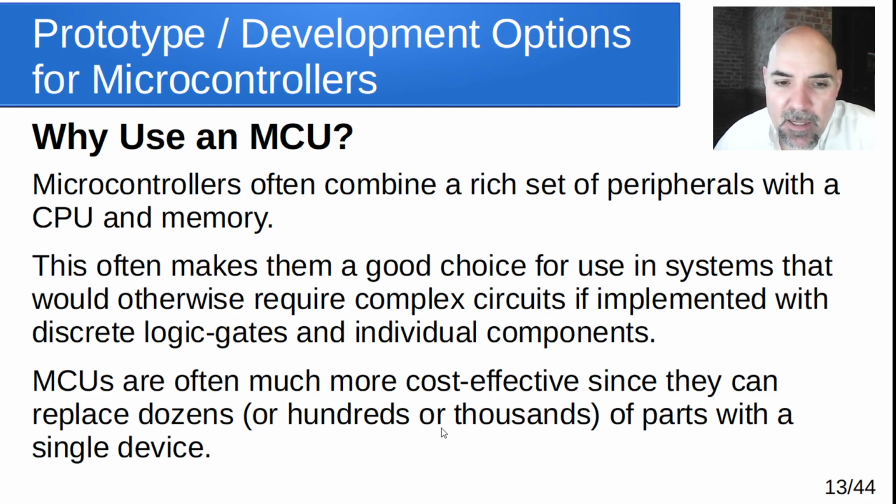And they're also very cost effective for two reasons. One is they replace a whole bunch of chips with one chip. The other one is that the more parts you have to place on a board, the more the cost of circuit board real estate is. The bigger the board, the more it costs, the more time there is soldering it, the more expensive it is to make. And then the other part about microcontrollers that makes them valuable is that because there are hundreds of thousands of choices, there's a lot of price competition there, so they tend to be very low cost.